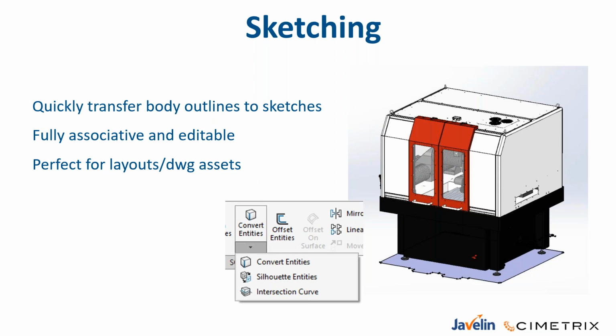But somewhere that I foresee it being used is with our SOLIDWORKS electrical users or anyone working in a 2D environment who wants to maybe do a 2D layout for, say, an electrical panel. In that case, they're designing the 3D component in SOLIDWORKS, and then they say, well, I want my 2D footprint. Well, you can now create that sketch, and then you can export it to a DWG or a DXF to actually create that asset. So it's a very cool way that we can now tie the 3D into the 2D a little bit better.